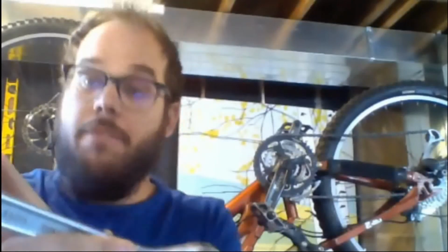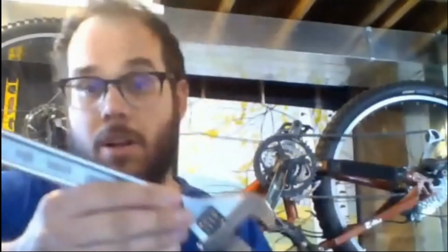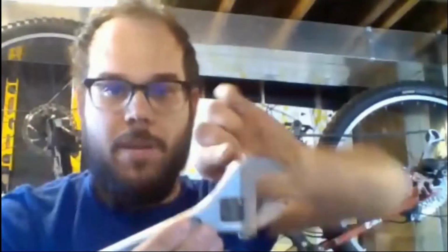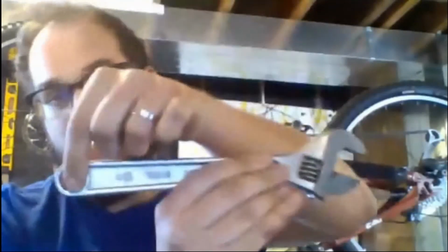And then, of course, the forces we can compare. We can compare how much force we put in here and how much force we get out here. And that is a thing called mechanical advantage. And we can also do the same thing with how far the system moves. So how much this part here turns in the middle versus how far the handle moves. And that gives us our speed ratio. So that's basically everything when we're talking about machines.